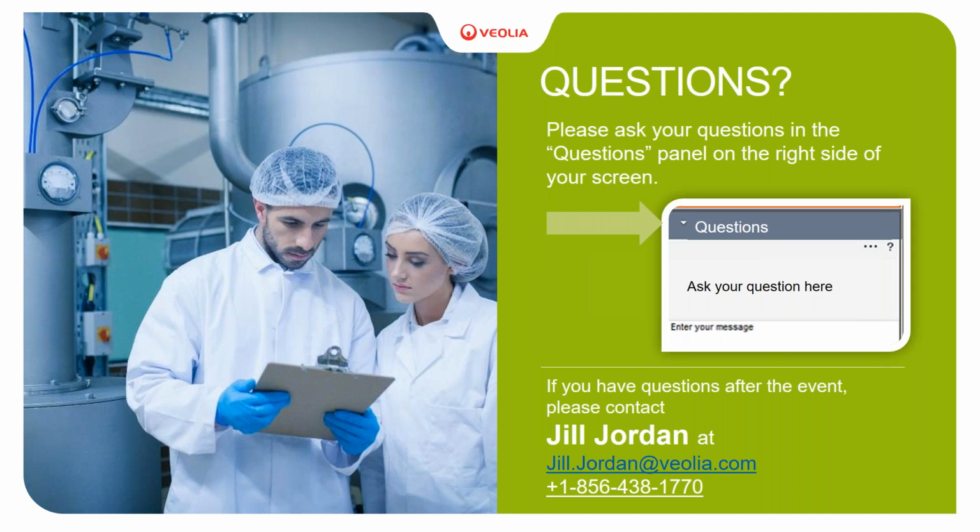And you should be doing a sludge profile at least every other week. I know some of my older customers are only doing it once a month now. But we recommend doing that once a week. And you'll notice that as you get up towards the top of the reactor, typically the concentration of the biomass decreases.